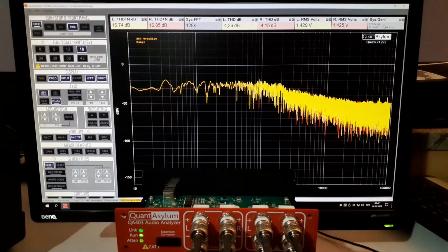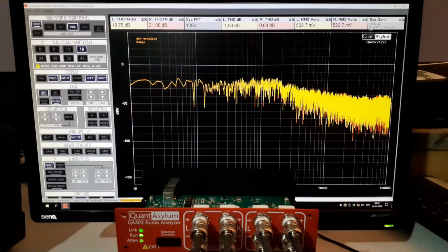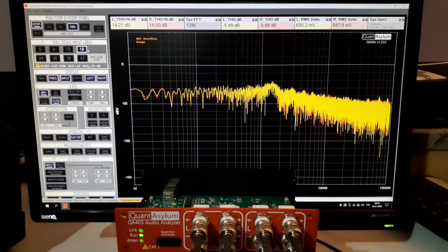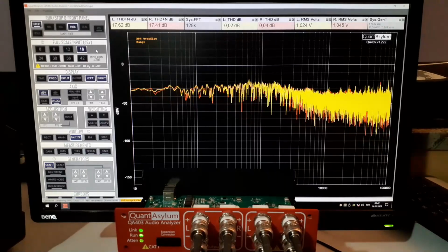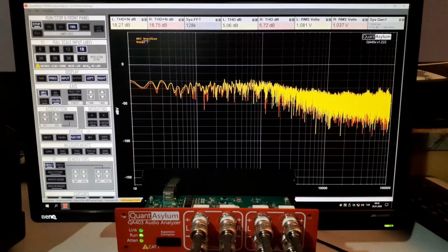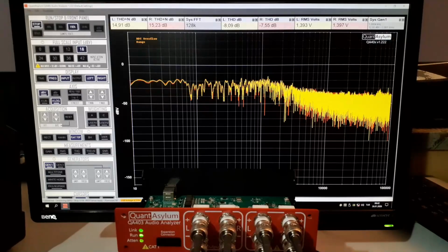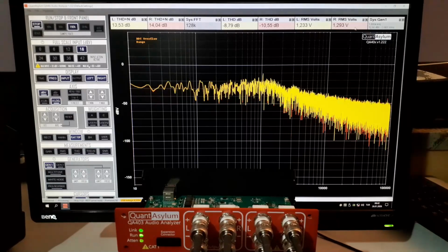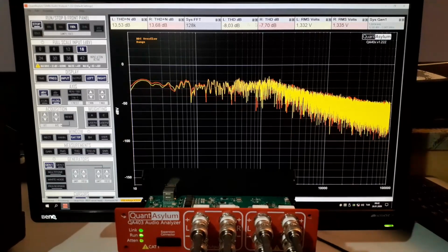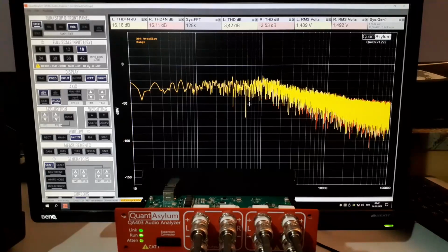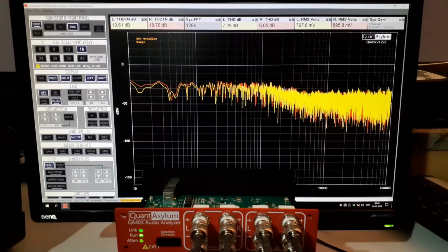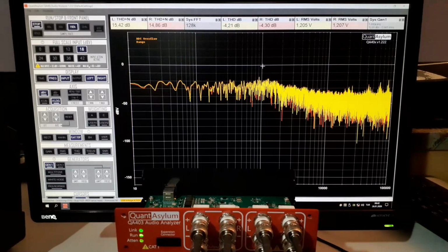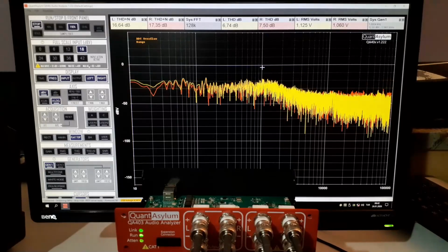I set my generator one output to 1 kHz, 12 dB volts RMS output. My input attenuator setting is correct, but it says ADC overflow, and it's not. In this window, everything is going crazy. Everything is false. Everything is wrong. This noise floor is ridiculous. There is also no 1 kHz sine wave tone.